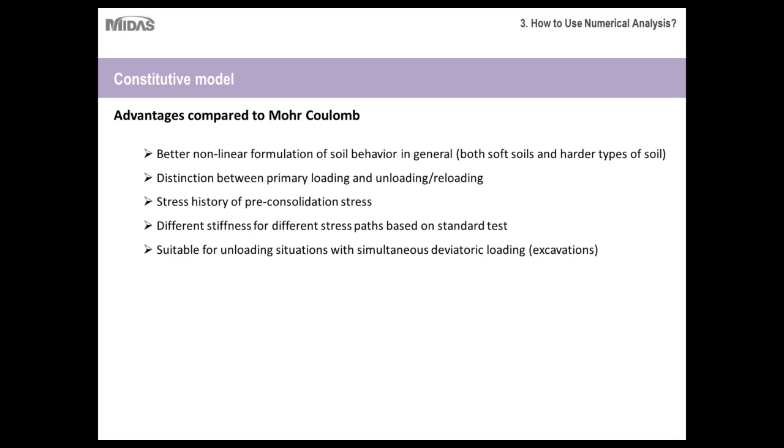This is also essential when you want to do a detailed analysis of deep excavation and unstable soil strata, because as you go deeper into the earth, you are taking out a huge chunk of earth mass, so you are causing a lot of earth load to be removed from the soil strata. It can result in huge heaving at the base of the excavation sites, which could be very critical.